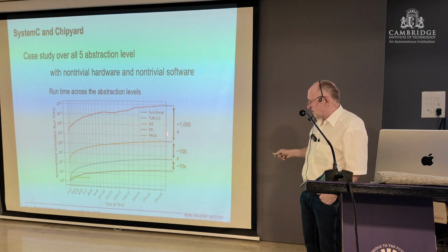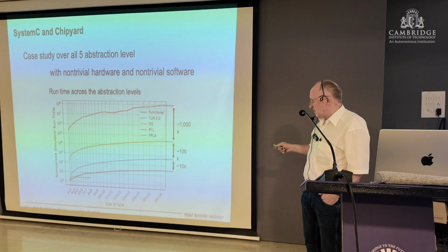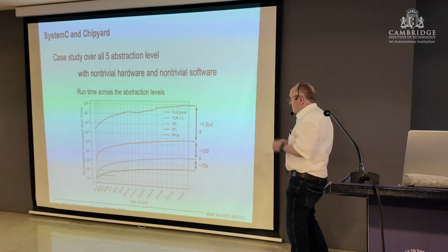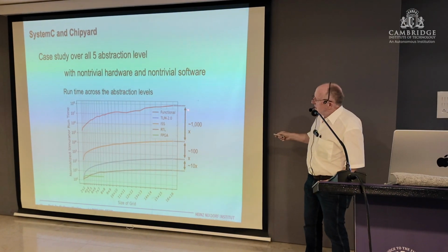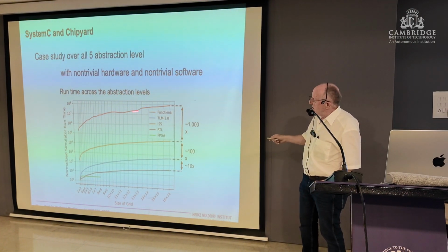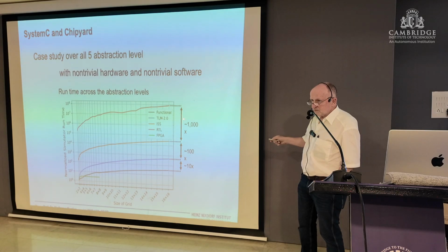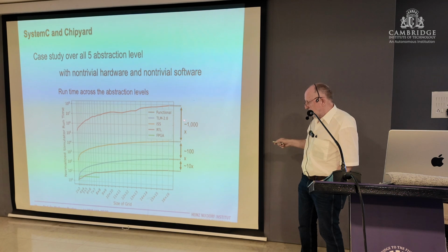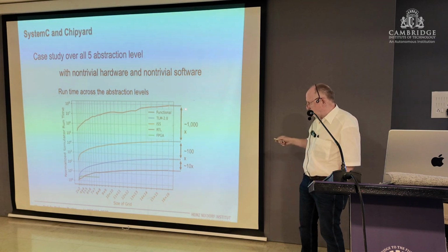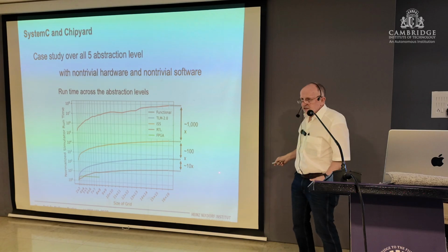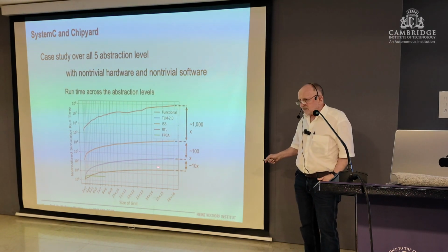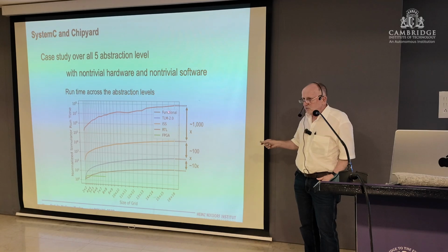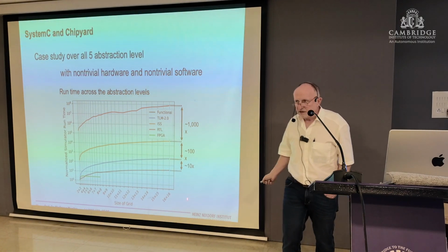And here comes the real bottleneck. We have the RTL simulation, which is pretty slow, and this is our bottleneck we have to solve. Compared from here to here, we have 10,000 and 1,000 and 1,000, which makes a million, which basically means one simulated second here makes two weeks of simulation. You see the problem.